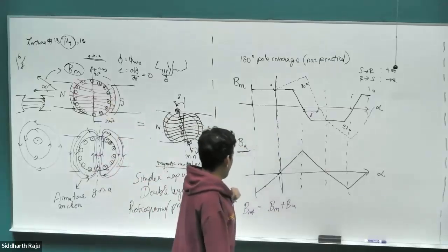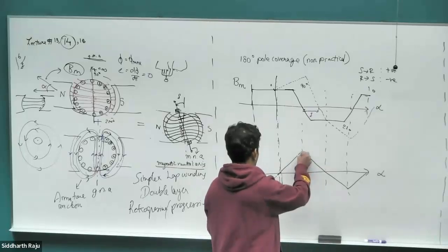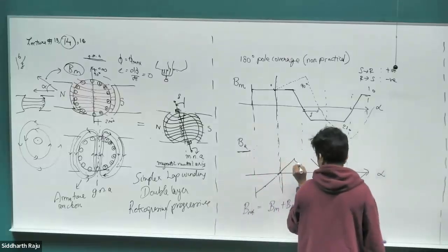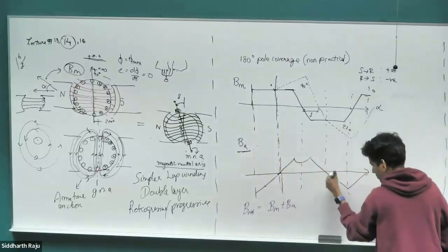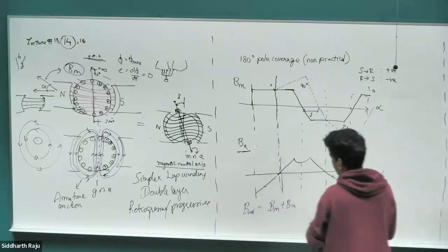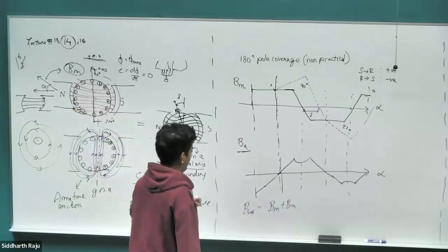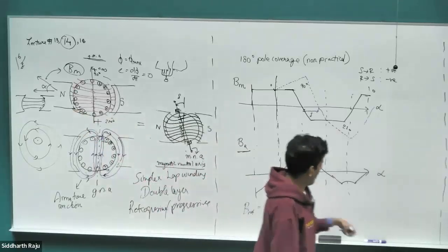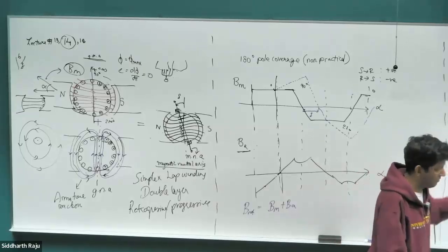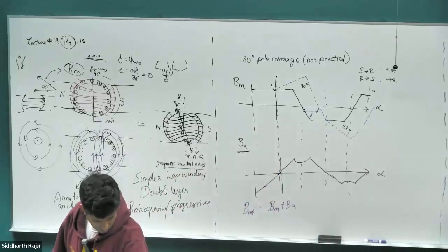But the biggest advantage that we get is that this waveform that I had for the B field is no longer going to look like this. We are going to significantly reduce the peak of this B field by just introducing this additional length in the air gap, the saliency that we have, because our H is still the same. H does not change. Right? LG has now increased in that equation that we had there. It was the same H1, H2 there.